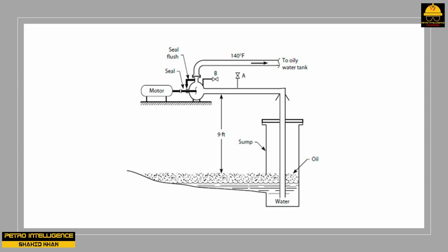But do such pumps require NPSH? Absolutely. All centrifugal pumps have some NPSH requirements. What, then, is the available NPSH to the sump pump shown in picture? The physical pressure at the suction of the pump is the pressure at point A. The pump was lifting water from an oily water sump. The water level in the sump was 9 feet below the center line of the pump's inlet.